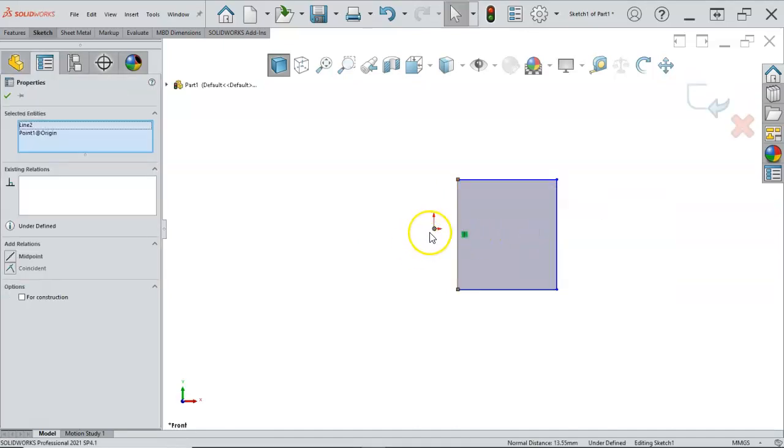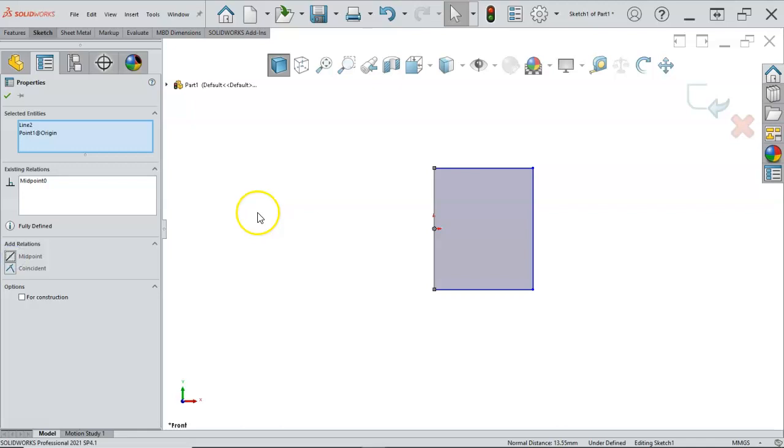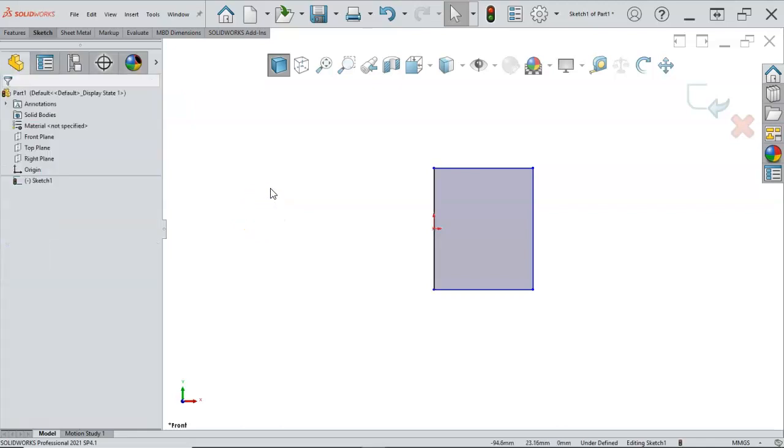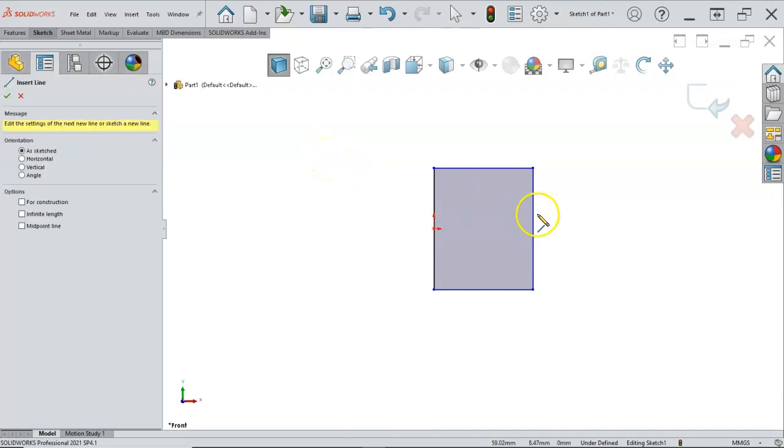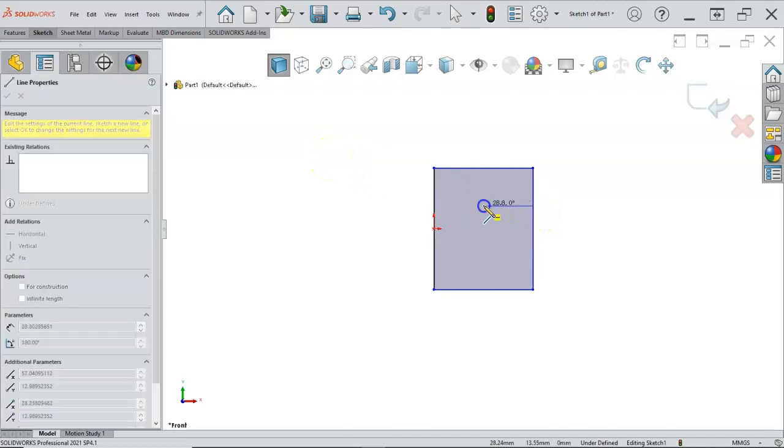And then I have selected the origin and control selected the vertical, and that can be at the midpoint. That's handy since this does have symmetry in it, that I can take advantage of that. Let's do this with the line, and then I'll back out of it and introduce a new tool.